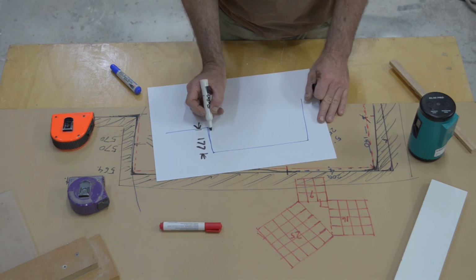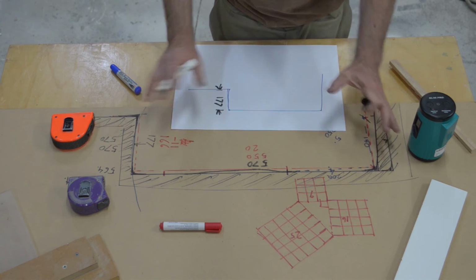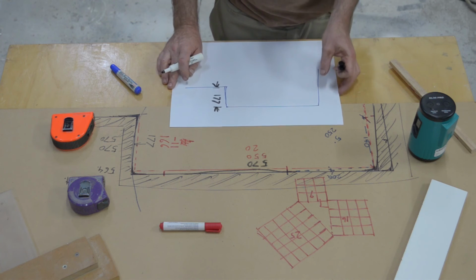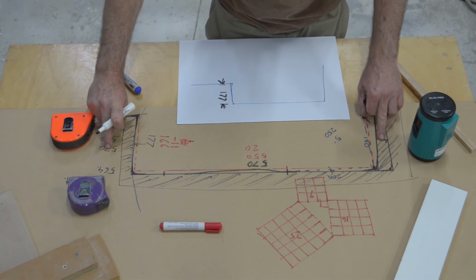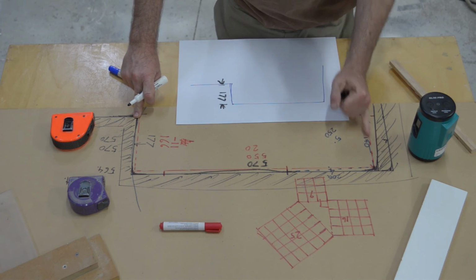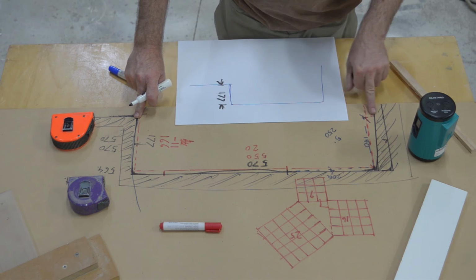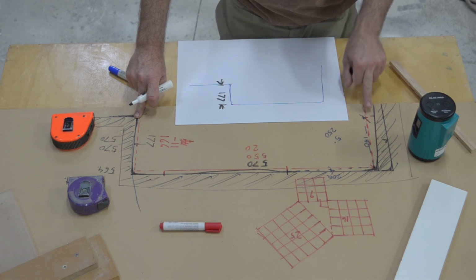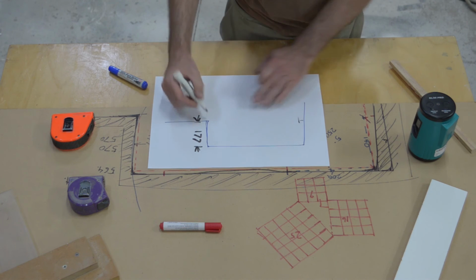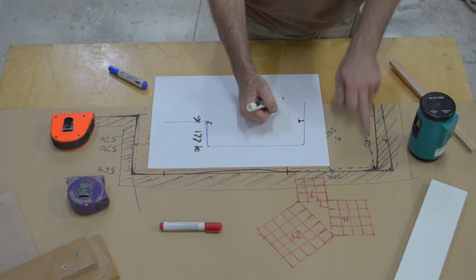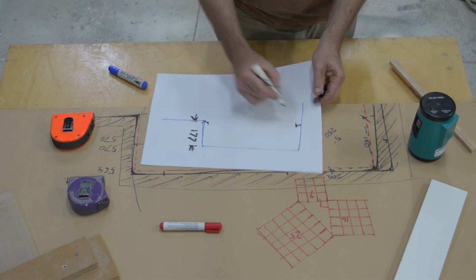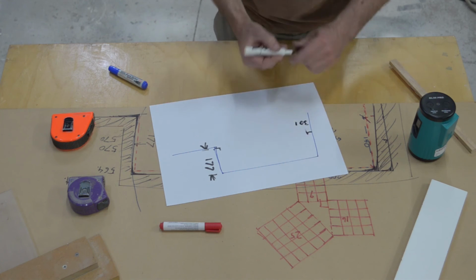But what I will have is the cabinet itself is going to be designed to be 150 because of how I naturally work. Okay, the width there is 570. Oh, sorry, here was 570 at half depth and the front edge was 570. But I did go through the process of assessing that wasn't square. Either way, it was telling me there's some fishy business over here. So I'm going to build in a 30mm infill on this side. And the same there. Just because I saw, even with my little Pythagoras method, it alerted me to the fact that there was an error here. So I might make a note, 30 infill. No, terrible.